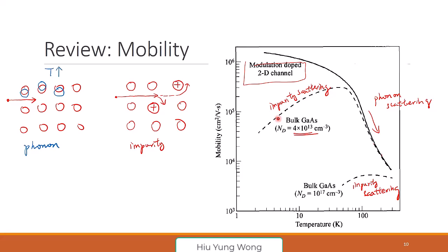For example, electron-electron scattering. You have so-called space charge. Because now you fill up the vacuum with electrons, it's more difficult to inject more electrons. So you slow down the electrons. That is what they call space charge transport. But this is a great question. It brings out what is the meaning of mobility. Mobility is an averaging effect.